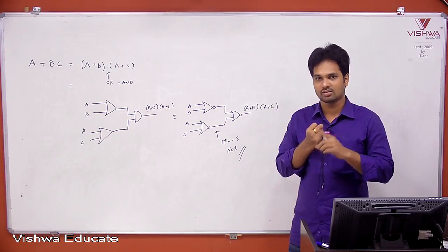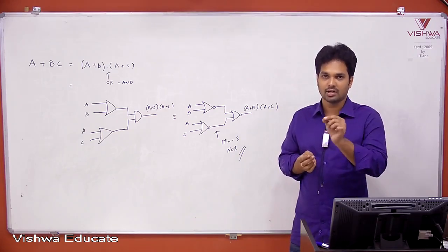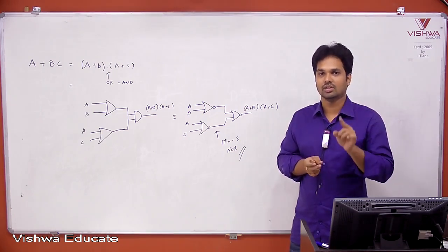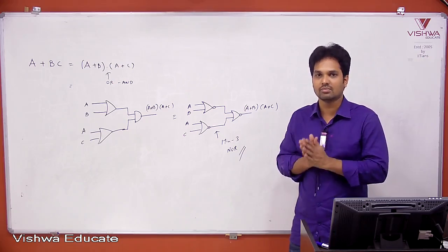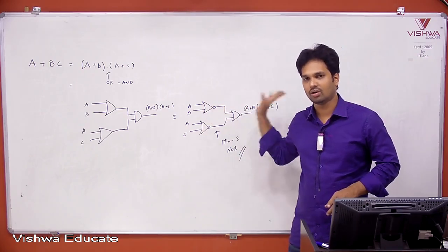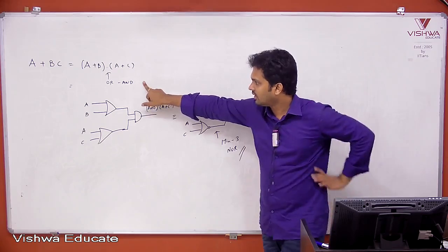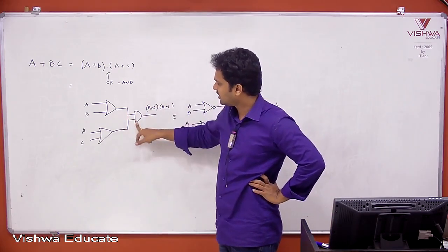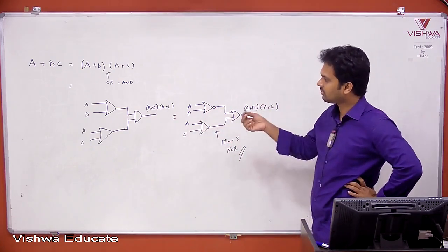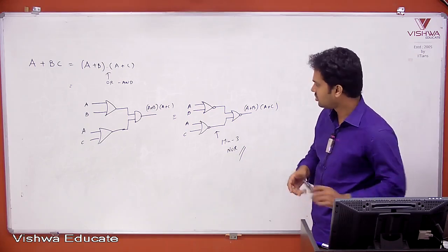If it is XOR or XNOR, the standard answers I have already given. If it is a product function, you can go by the bars method. Last way, if it is an AND OR function, go blindly: any AND OR is blindly NAND. Similarly, any OR AND is blindly NOR. No need to draw this. If you observe it as OR AND, how many gates? 3 gates, so 3 NOR. Or you can directly draw this figure, nothing wrong. In place of OR AND, you can replace it with NOR followed by NOR. You can copy the solution.